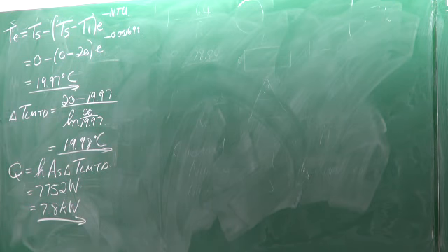Right. Now, if I go back to where I've started, I've made an assumption, and that assumption was my outlet temperature is going to be minus 20. Therefore, my bulk temperature is minus 20 plus 20 divided by 2, 0. Obviously, that was not a good assumption. Do you agree? So, if you now redo it, you need to realize, oh, that wasn't a good assumption, I need to redo it.